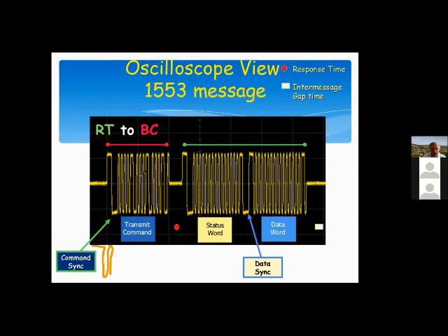It turns out that ground on one box may not be the same as ground on another box, and therefore there's room for confusion. However, here, if this signal is high, in other words, it's at plus 3.75, then the mirror image is going to be at minus 3.75, which means that the gap between them is 7.5 volts.